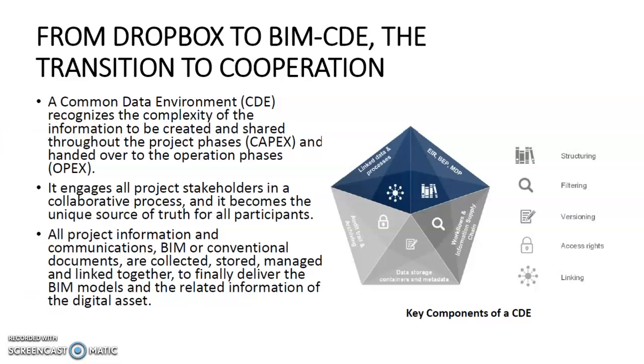A common data environment recognizes the complexity of the information to be created and shared throughout the project phases, right until the operation or the handed over phases. It engages all stakeholders in a collaborative process, and it becomes the unique source of truth for all the stakeholders. All project information and communications, BIM or conventional documents, are stored, collected, managed, and linked together to finally deliver the BIM models and the related information of the digital asset.